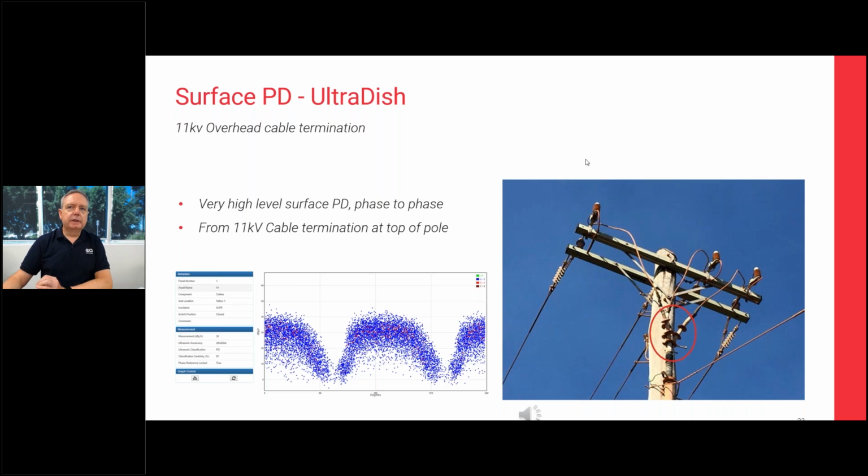So surface discharge activity is generally very easy to identify exactly what's going wrong once you've taken that outage, or once you've taken the opportunity to look at it during the maintenance. The main thing with this is to target which chambers to open up and which are appropriate.